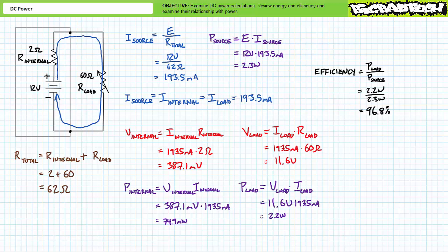This is what is known as the working voltage of a battery, which is in contrast to its nominal or nameplate rating of 12 volts. Given any power consumed by the internal resistance is considered a loss, we would expect the battery to exhibit some small degree of temperature rise, accounting for this inefficiency.